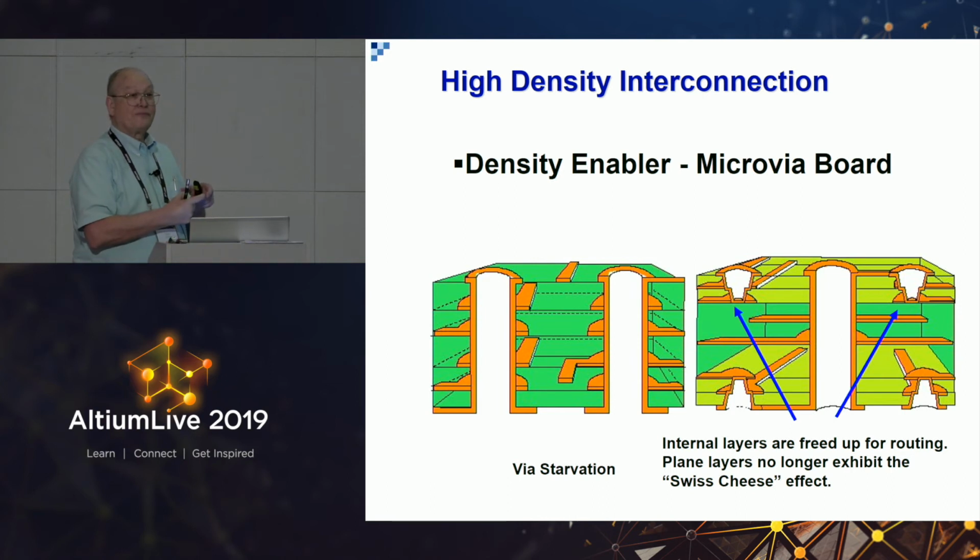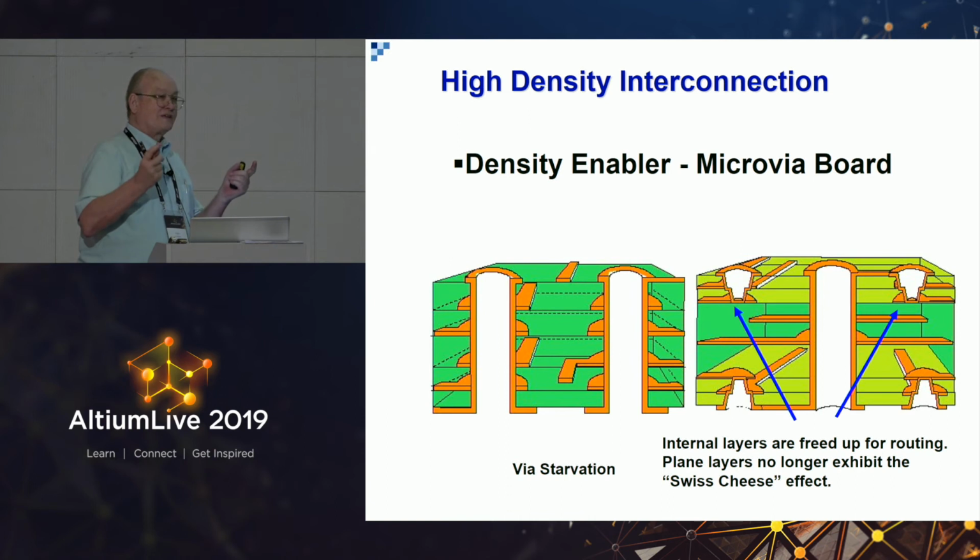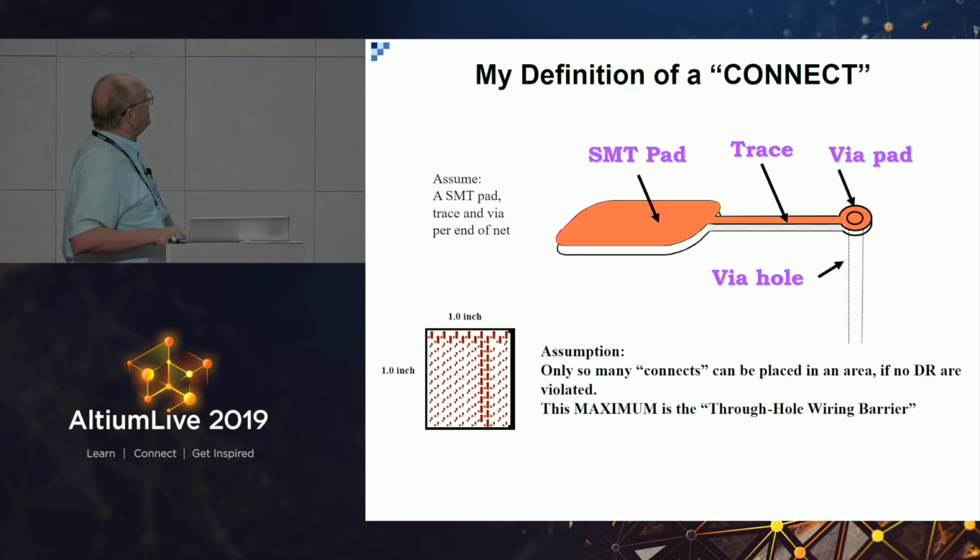Underneath the BGA, we've turned that reference plane into Swiss cheese by holes like this going all the way through it. So we have enormous power drops and problems with current within the BGA because we've eliminated all the copper. And that's a big problem with fine pitch, because you have to keep the keep-out. We've got no copper left to transmit. So consequently, the temperature rise is very extreme, which leads to all kinds of power integrity and signal integrity problems.